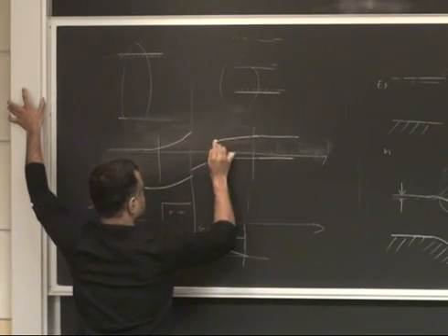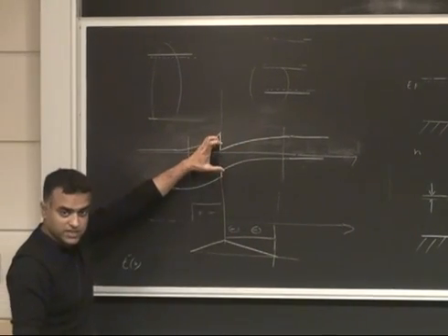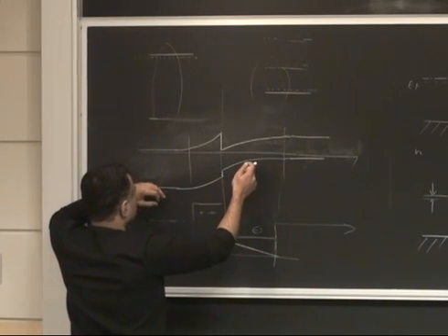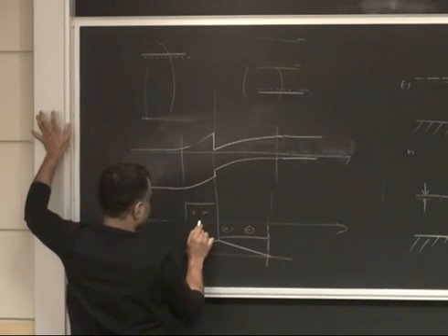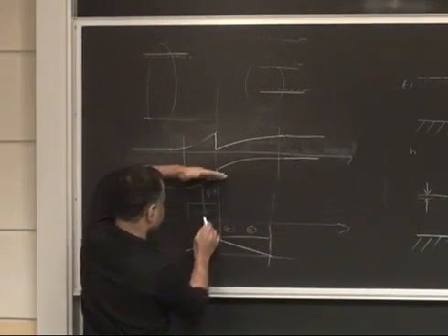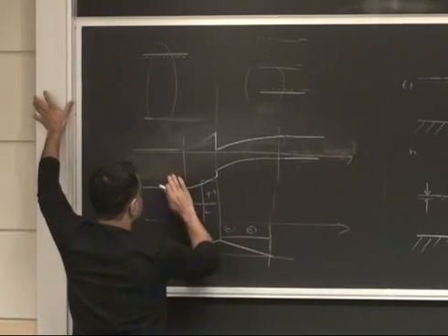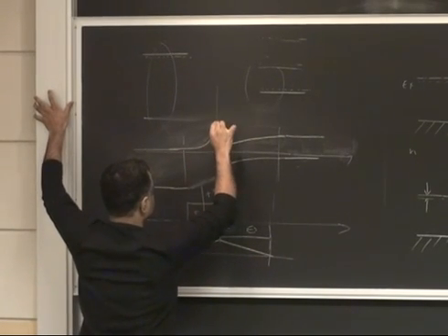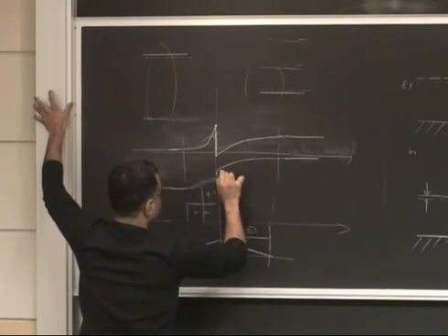So what we are really discussing is that you can have various situations depending upon the doping levels and conduction band offsets, right? So for example, let's say I dope the n side region rather heavily. I think you realize if I dope it heavily, I will have a bigger doping density, and therefore the depletion will be smaller, right? And so what happens then is instead of something like that, it'll go up sharply, but it won't kind of drop. So the band offset doesn't change because of doping, and you might end up with something like this, okay?